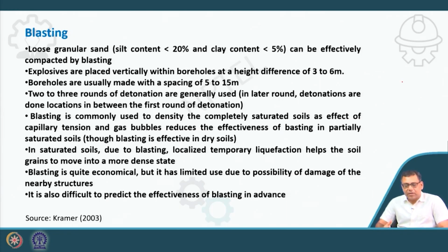Generally, we prefer this technique for saturated soil, and due to the blasting, the localized temporary liquefaction helps the soil grains to move into a more dense state. Blasting is quite economical, but has limited use due to the possibility of damage to nearby structures.